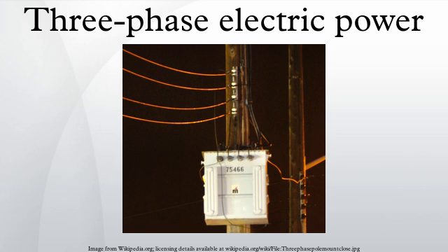Where a delta-fed system must be grounded for protection from surge voltages, a grounding transformer may be connected to allow ground fault currents to return from any phase to ground. Another variation is a corner-grounded delta system, which is a closed delta that is grounded at one of the junctions of transformers. 3-wire and 4-wire circuits.